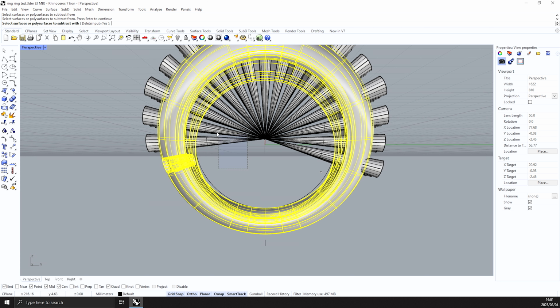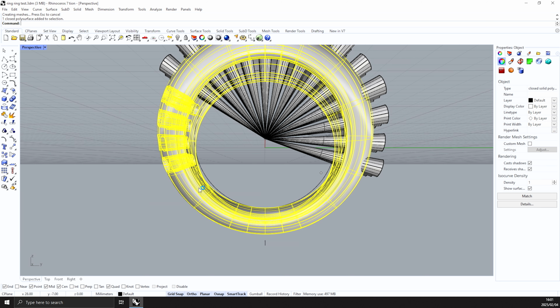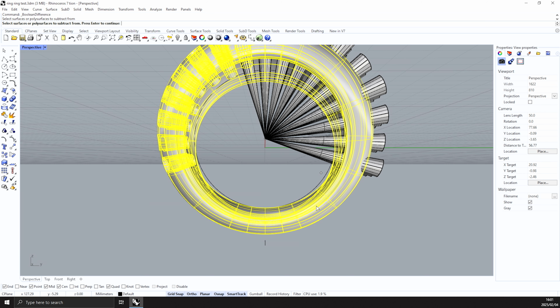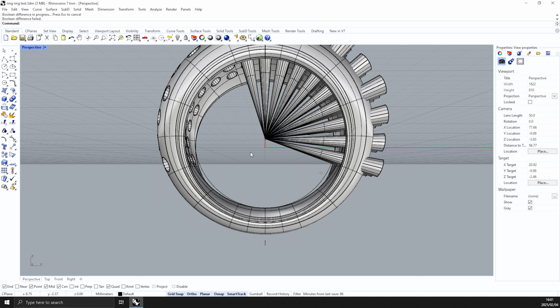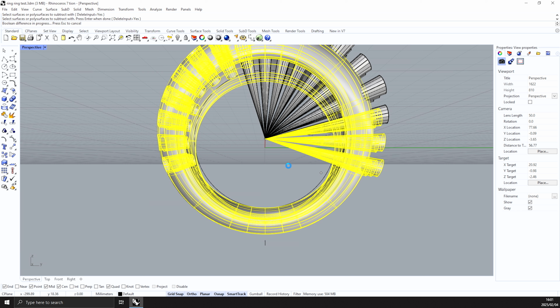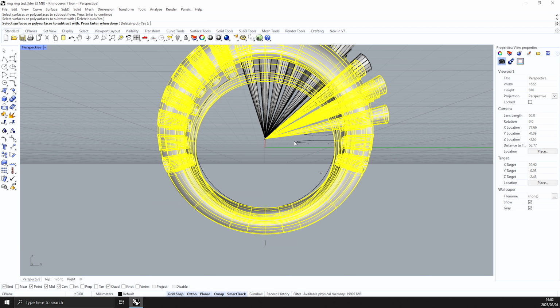You cut with you guys. It's a bit more of a complex Boolean process, so it takes a little bit longer. Let's try and push. Boolean fail. It was a little bit too complex. I selected too many of them at the same time, and then that happens, and your Boolean fails. So let's just do a smaller amount of them at the same time.